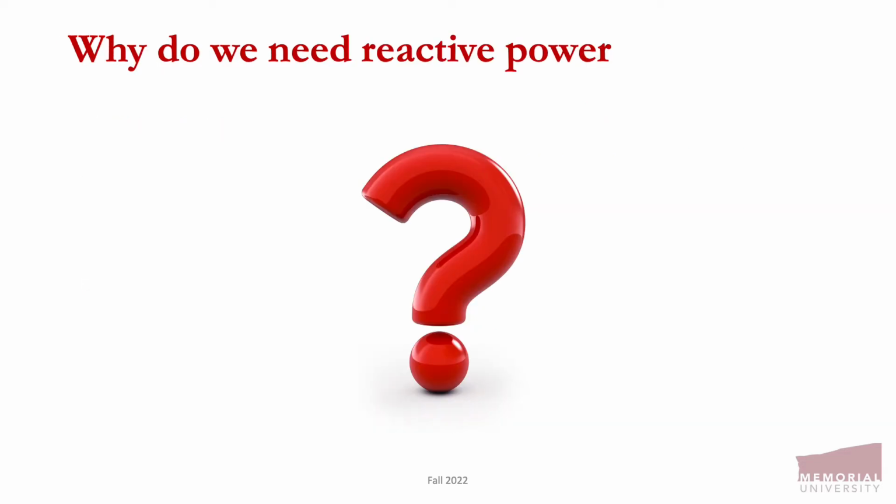So why do we need reactive power? In resistive load, the current produces heat energy which produces the desired output. But in the case of inductive load, the current creates the magnetic field which further produces the desired work. Therefore, reactive power is the non-working power caused by the magnetic current to operate and sustain magnetism in the device. Reactive power is required to maintain the voltage to deliver active power through transmission lines. When there is not enough reactive power, the voltage sags down and it is not possible to deliver the required power to the load through the line.